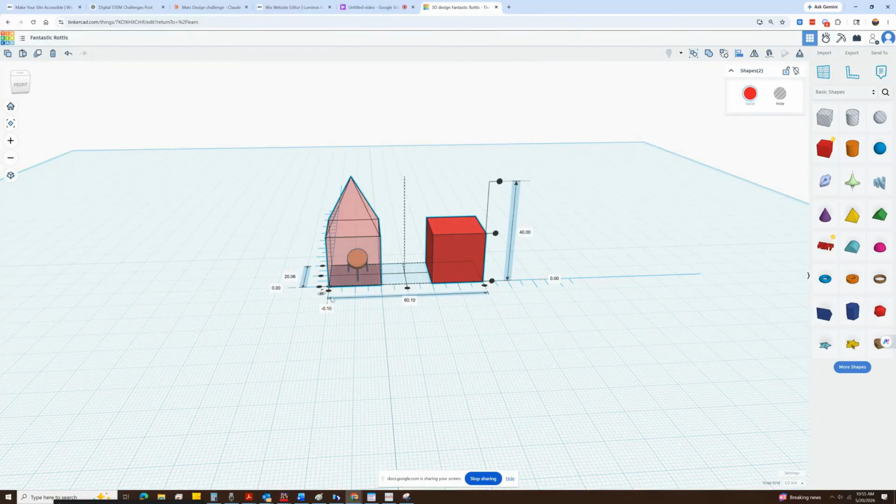When you click on this left front dot, this cube is going to move and align with this object over here. When you click on the center dot, they both align and come to the center. And when I click on this dot, this object is going to move to this spot, right? If you just hover your mouse on these dots, you will see what's going to happen.